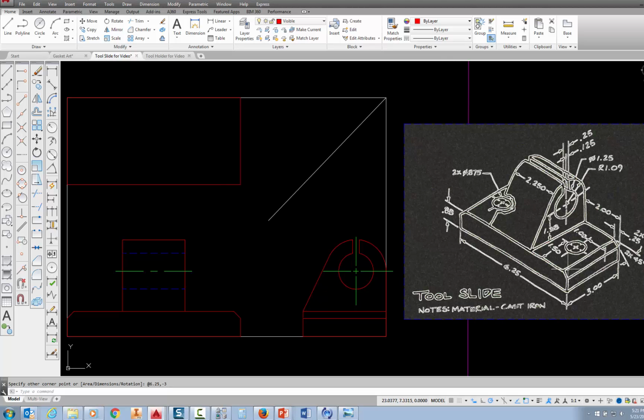So let's add another feature. We have a chamfer, and you can see it right here. If we project a line up from this corner, we're going to have a line going all the way across, and if we project one from this corner, we'll have a line going all the way across. So let's pick the line command and come down here to this corner and put our mouse there until it says endpoint. Then we're going to follow the dotted line up, and we're going to pick for the first time right here at this intersection, and we'll pick right here at that perpendicular. Now, you would think I would do the same thing over here, but I intend to do something a little bit quicker. I'm going to mirror that line over to this side in a couple of minutes here after I add some other things.